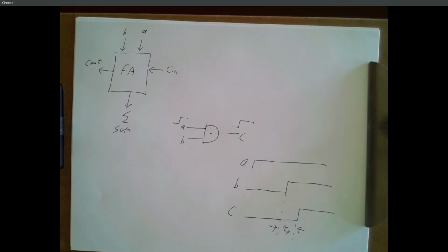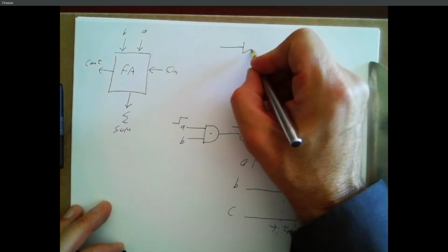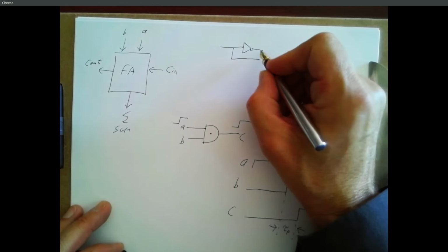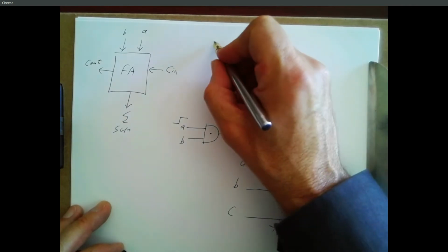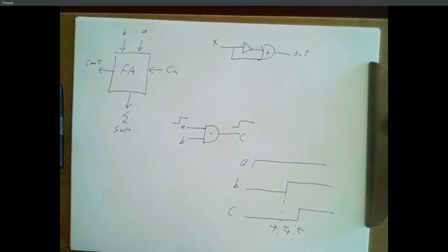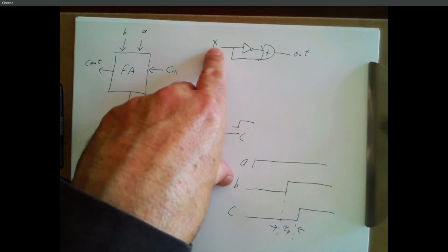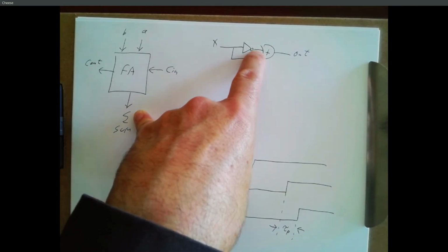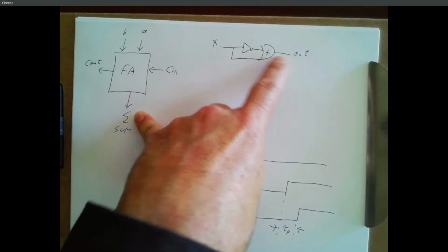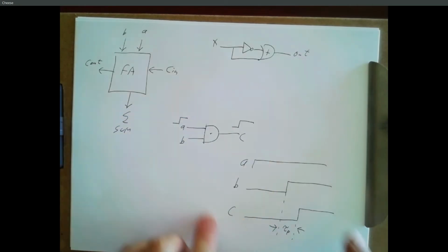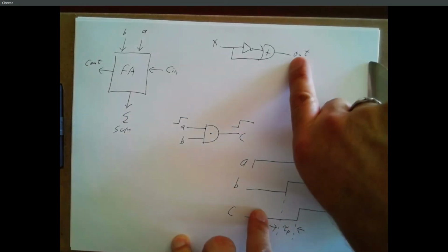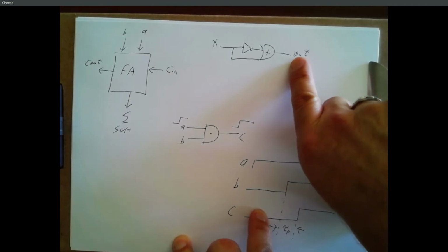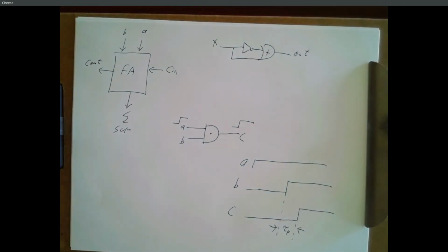And so that introduces the possibility of glitches, and we've looked at some circuits that have glitches based on this behavior. So the one we actually did in Verilog was something like this. The output should always be 1, because if x is 1, we've got 1 going into an OR gate. If x is 0, that gets inverted to a 1, we've still got 1 going into an OR gate. So in either case, we expect the output to be a 1. If you actually make the timing diagrams, there's a glitch where the output goes low. It happens when x changes from 1 to a 0.